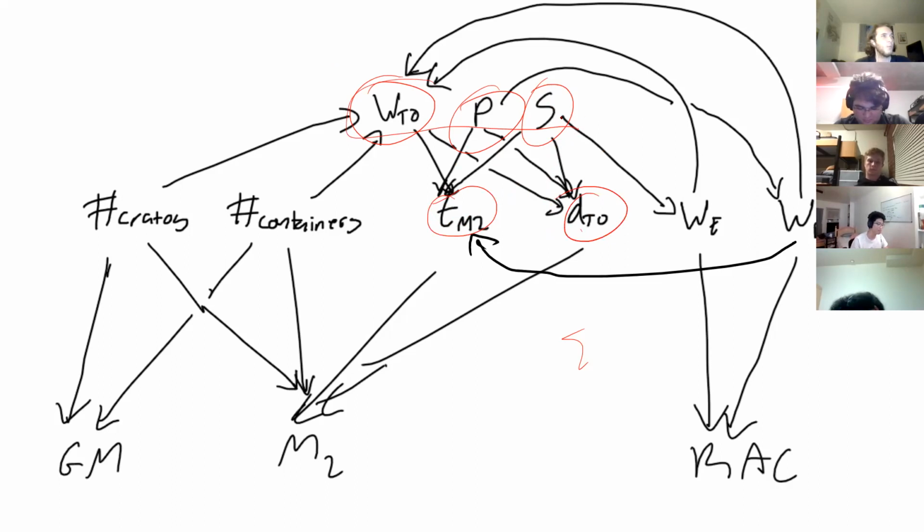The wing area affects the empty weight, as we talked about, with the material buildup and stuff like that. The power that you're going to draw affects the battery weight. Both of those, which are in and of themselves scoring parameters, also affect the takeoff weight, along with the payloads.